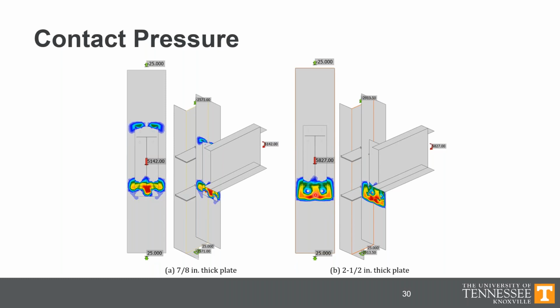It's a stiffer and stronger plate that can accommodate those higher stresses out at the far end. So the lever arm between the bolts and the contact pressure is just increased here with respect to the thinner plate, and certainly with respect to the traditional calculations. Another example where we're seeing higher strengths from IDEA StatiCa, but for what I would argue are very good reasons.